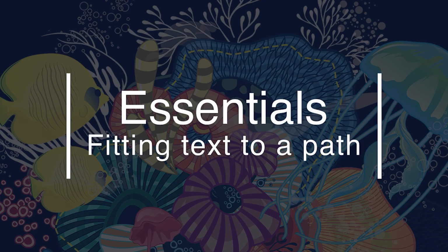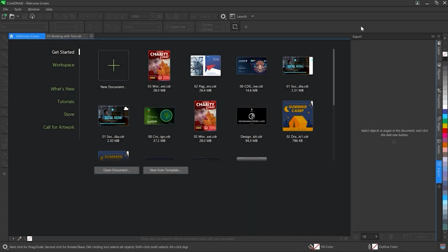Fitting text to a path can be achieved in CorelDRAW by adding text along the path of an open object such as a line or a closed object like a circle. This can be done using the text tool from the toolbox or by using the text to path command from the text menu. CorelDRAW offers a variety of controls, allowing you to adjust the position of the text on the path and mirror text along the path. This activity continues from the previous one.